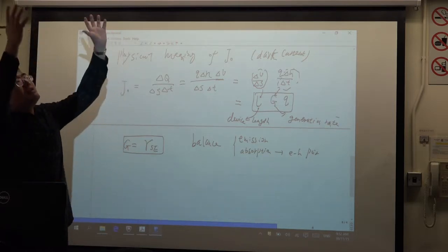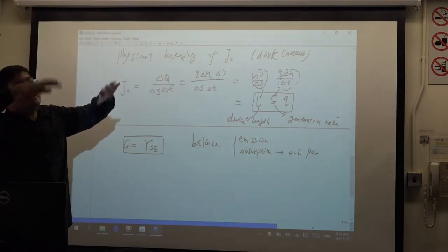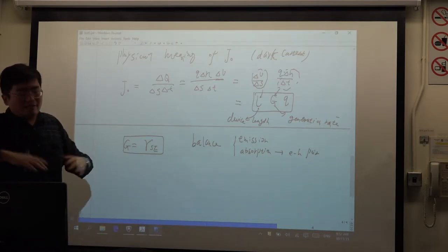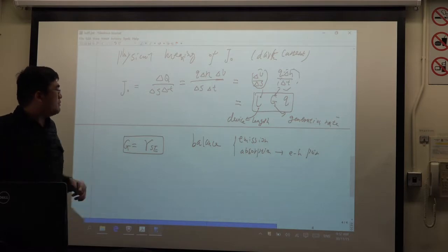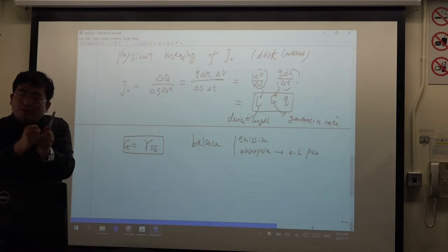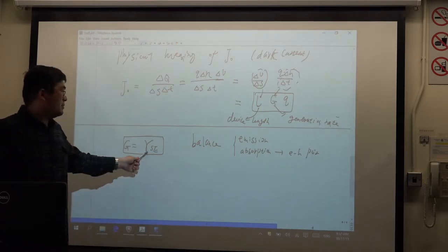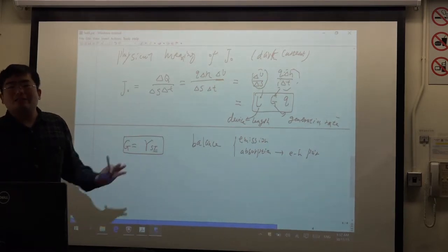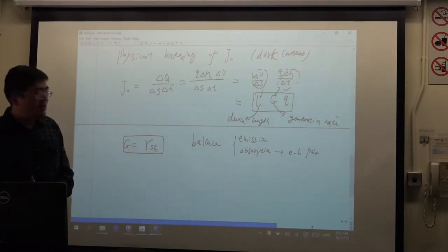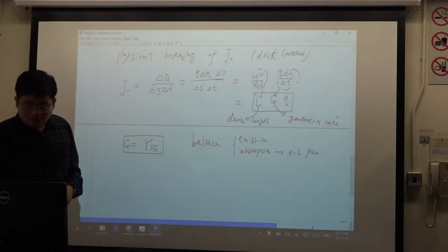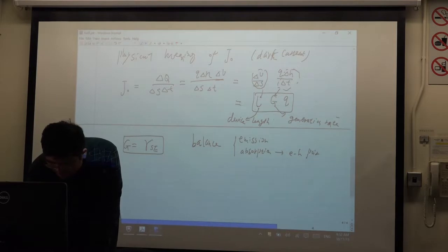That means in a vacuum, the electromagnetic field will fluctuate, and this fluctuation field will generate electron-hole pairs. The electron-hole pairs all recombine and emit light. So this is spontaneous emission. We did not consider any non-radiative decay, so this should be balanced. The generation rate is just the spontaneous emission rate. How to enhance the spontaneous emission rate?